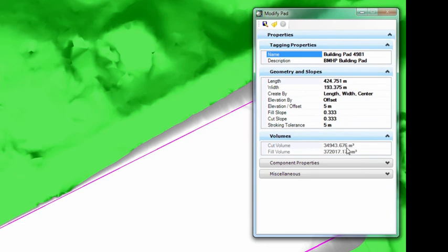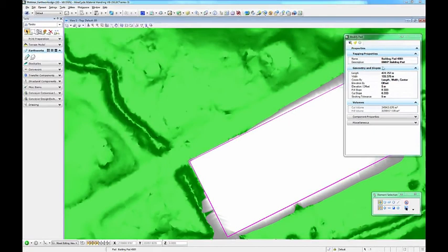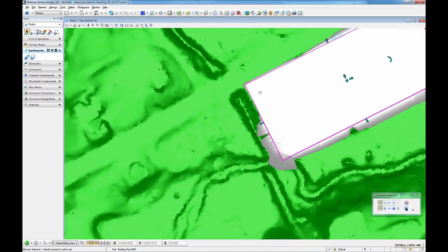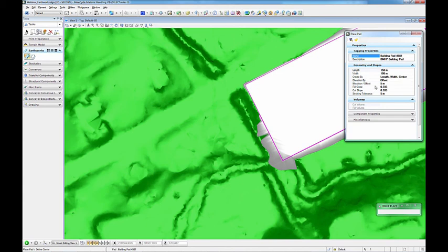Accurate cut and fill calculations are dynamically displayed and are also shown in the site pad properties. This allows analysis of the cut and fill requirement so that the possible options can be quickly assessed and either accepted or rejected. The ability to create a drainage pond from the site pad tool is achieved by simply specifying an elevation which is below the terrain.